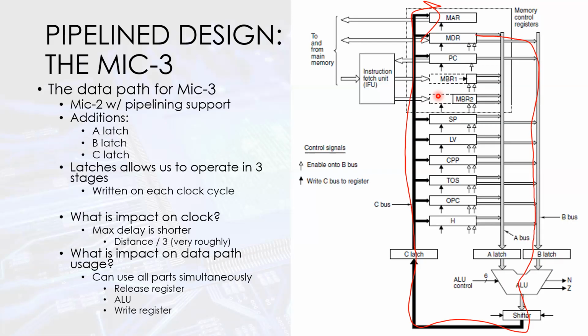I'm assuming that the ALU is on this one. So the other two have to wait to transition until the ALU finishes? In this example, we have a hypothetical, we don't really have real numbers on it. So in theory, I can see the argument the ALU is going to take a little bit longer, but if that's the case, then whatever your longest stage is, that's going to be your cycle length.